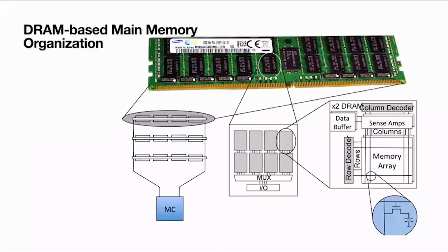If you see here, inside the CPU tower, or even your laptops, on the motherboard you'll have a set of DIMM slots, dual inline memory module slots. Here there are 3 DIMM slots under the control of the memory controller, MC. In each DIMM slot, we put a DRAM-based DIMM, a dual inline memory module, which has pins at the bottom on both sides, and through these we read the data.